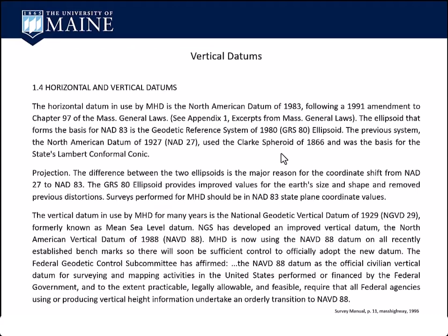And you'll have to work within whatever datum. There's 1,000 towns out there that never changed from 29 because as they built out their sewer networks, and it's all 29, the plans, and it's just a number, so who cares? Just keep it in 29. So that when people start tying into sewers and things like that, drainage, they can stay on 29. It's not a big deal. It's just you have to know what datum you're expected to be working on and find the appropriate control.